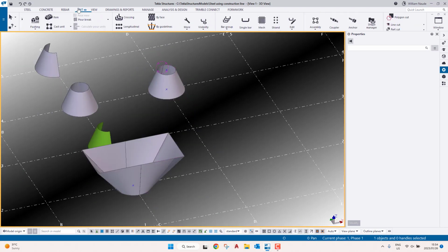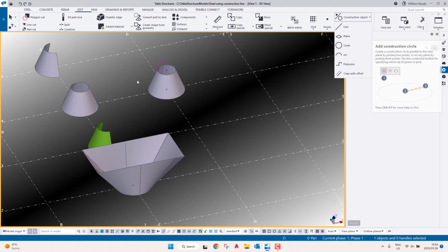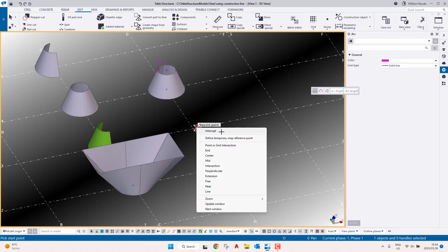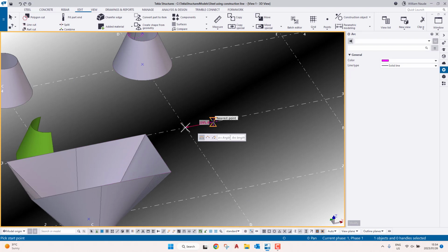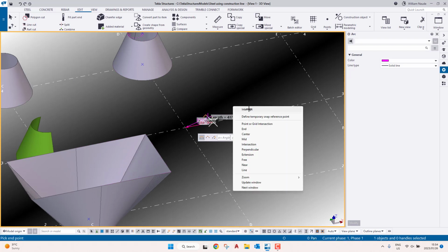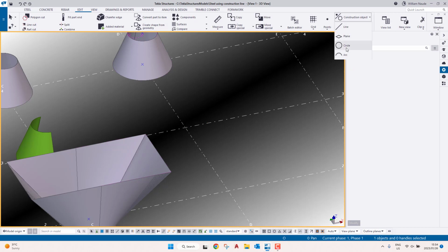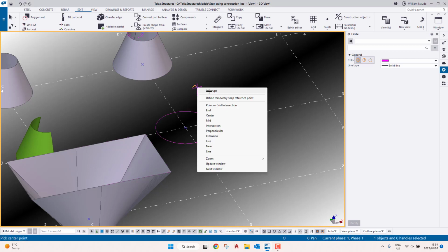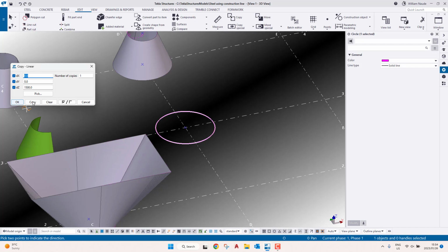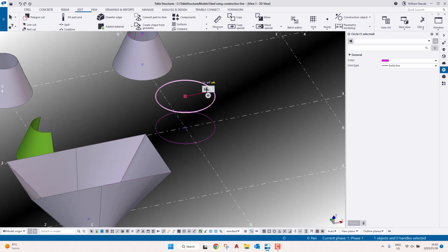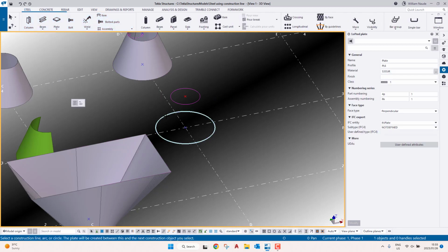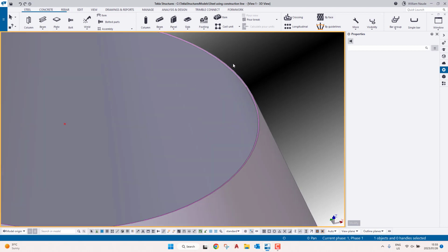Now the second function you can use, and like I said, you can use this function and it will work. But now if you use the circle, and we choose the construction line, click quick, 1197, there we go. So we're going to copy this upwards again and change this to 597. Go, steel, create, lofted plate, there we go. So now we have these two items.